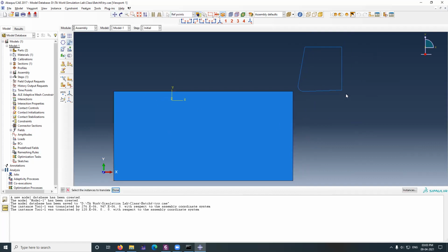So let's move the instance here. Done. Starting point is 0, 0. In the Y direction, I have to move 180 microns. Obviously, I have to move the tool not in the positive direction, but in the negative direction. So let me give 180 microns. Click enter. So this looks okay to me. If you are choosing RTS as 5, what do you have to choose? 60 into 5, so 300 microns you have to move down. So I'm okay with RTS 3.